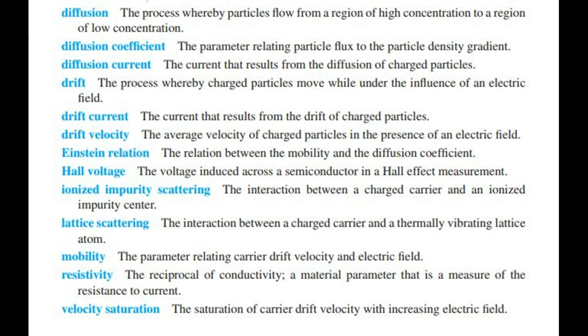Lattice scattering, the interaction between a charged carrier and a thermally vibrating lattice atom. Mobility, the parameter relating carrier drift velocity and electric field. Resistivity, the reciprocal of conductivity, a material parameter that is a measure of the resistance to current. Velocity saturation, the saturation of carrier drift velocity with increasing electric field.